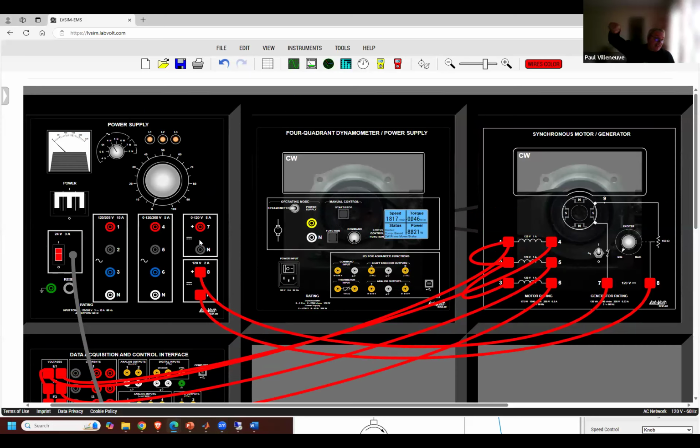And so when that magnetic field crosses through, it's going to get a peak, and then 120 degrees later, you're going to get another peak. And then another 120 degrees, you're going to get another peak. And those are phase shifts because you physically constructed the machine to have those windings 120 degrees apart.